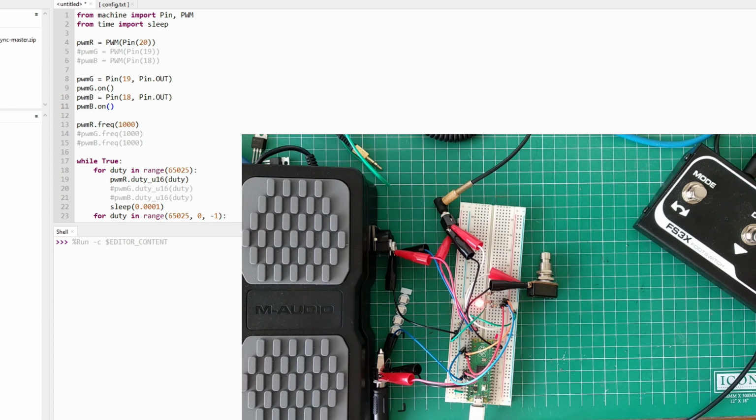Ideally, I would find something like that just for low power, low current diodes, that would be great. Remembering that traditional guitar effects can consume under 10 milliamps, so we need to make this reasonable, because my cheap power supply is driving a maximum of 120 milliamps.